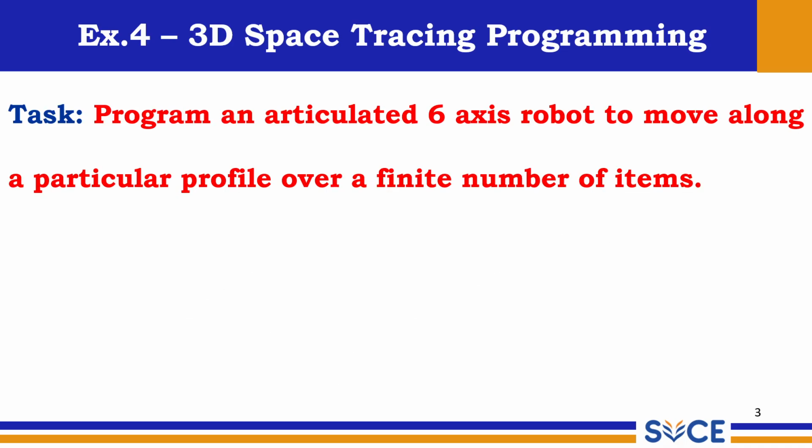So we'll understand the basic part. What is 3 dimension and what is 2 dimension? 3 dimension means x, y and z. 2 dimensions means usually we work on x comma y. Earlier programs were only with respect to x comma y. To recall, the home position of the robot is 470 comma 0. But here we'll be dealing with the third dimension also, so 470 comma 0 comma 855. This is the home position of the robot. Earlier we discarded the z direction, but here we'll be using it.